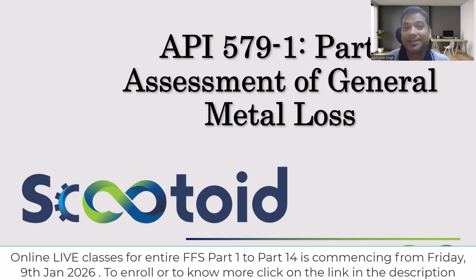You have done the inspection. If I have given 3 mm corrosion allowance for 20 years, what is my corrosion rate every year? If I have 3 mm corrosion allowance, which I've allocated for 20 years, what is my corrosion rate? Give me that. 3 by 20. Right? I read few more responses. 3 mm corrosion allowance spread for 20 years. Yes, 0.15 mm per year.